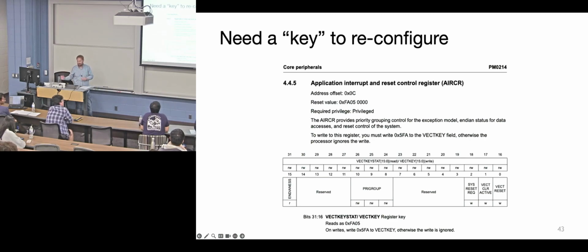So, how do we use the key then? Can you use this on one of the registers for the interrupts? Let's see, there's a register that's the key. If I read through the data sheet, there's a register, and you have to take this value and put it in there. You read through the data sheet, say, okay, that's my key, and put it in that register, and that unlocks it. So then you can go reset the preemption and the sub-priority priorities.